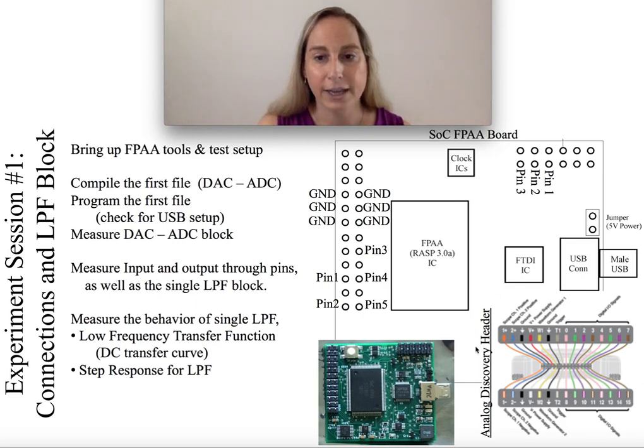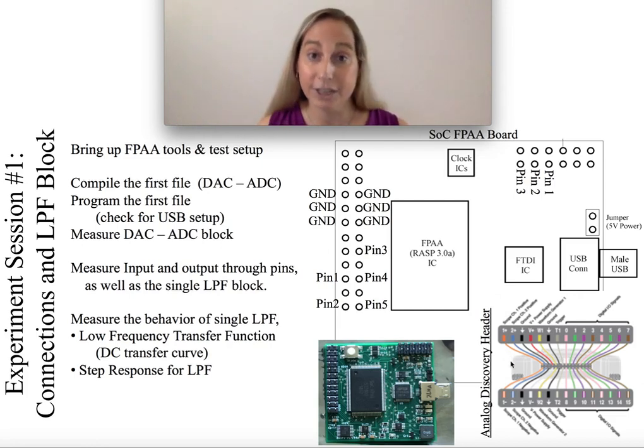You might also have a scope-like device, like an Analog Discovery block. Again, you want to watch where your input scope channels are, like 1 and 2, plus and minus. You might be curious about where your voltage supplies and signals are, like W1 and W2 for the waveforms, and a few other things that you may end up wanting to use. There's a whole bunch of digital I/O, but start to know where your tools are. Fortunately, for a lot of the things that you're doing, you could get away with probably one or two USB-controlled structures running off your laptop, and all of this works great.